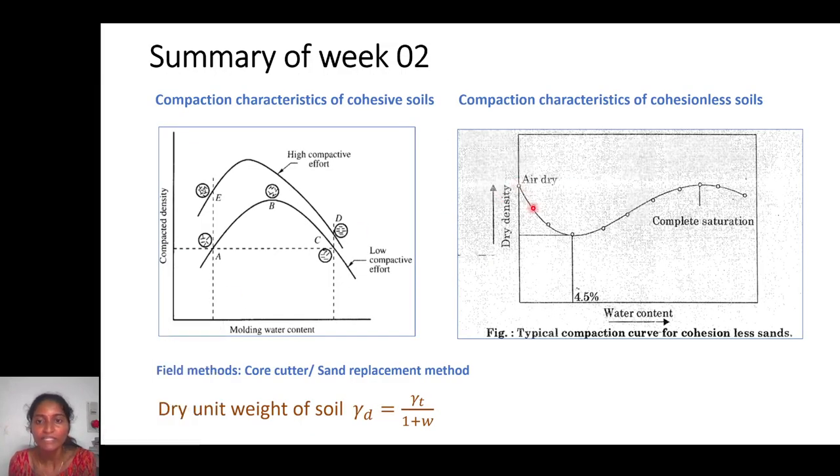due to the little amount of moisture I am adding, because of the capillary action, all the sand aggregates try to come closer because of the water. Whatever connected air voids are between them will form a capillary action. Water always wants to come to the top because the atmospheric pressure is higher. So the water at the bottom, due to capillary action, wants to suck to the top. When it is trying to come to the top, it also tries to make the sand move to the top.